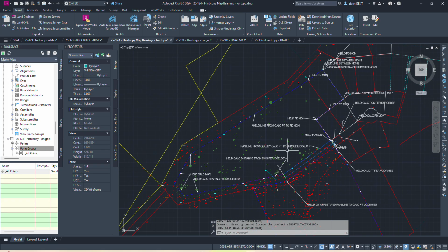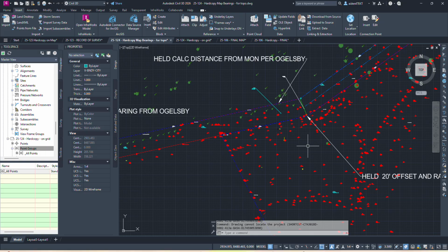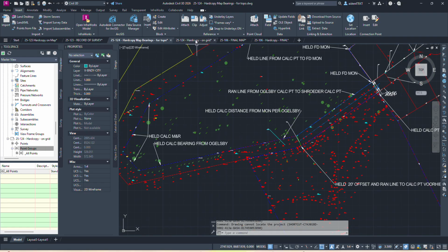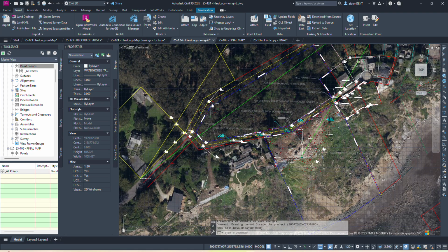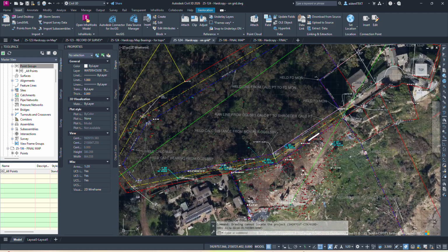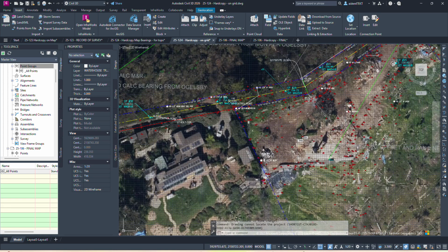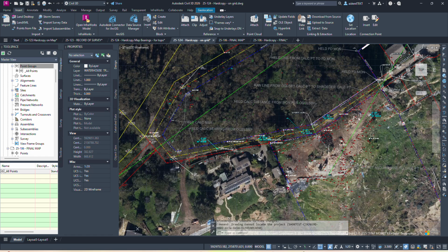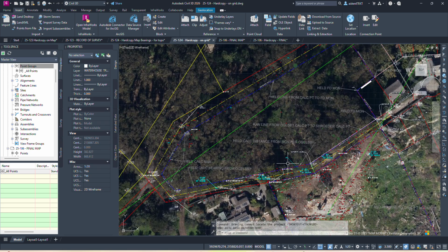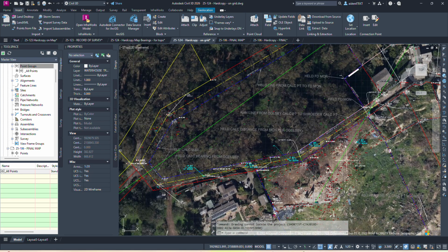Now, I decided to do it on my original grid coordinates. I did that so I can just fire up the GPS on this one base point here and start going with my rover. Because this is a processed GPS point, it has a known location, and I could broadcast from this and start collecting data, and all my project is rotated correctly based on these original grid coordinates.